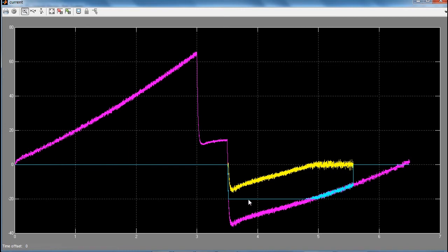The light blue response is the current going into the energy storage device. So because the currents went negative, the storage device is now charging up. I've set its maximum charge rate at 20 amps, so we see it charging. And then as the regenerated current drops below 20 amps, we see the storage device tracking that, so it's still bringing that current into the storage system.